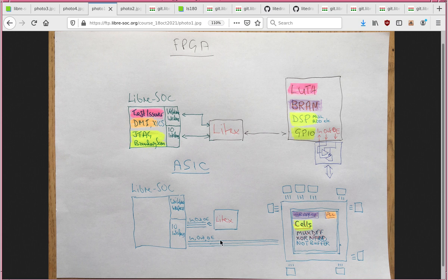Now, the in, out, and output enable here, which in LiteX gets connected as just a GPIO. That triplet of in, out, and output enable per pin on your interface needs to be passed right the way through the entire source code, the entire netlist, until it hits the individual pad, the IO cell, containing that in, out, and output enable.